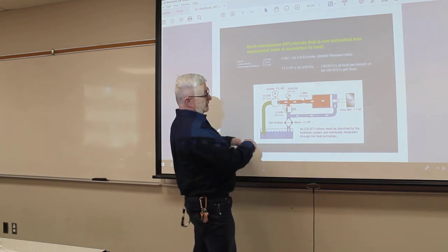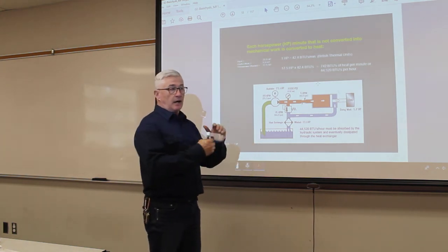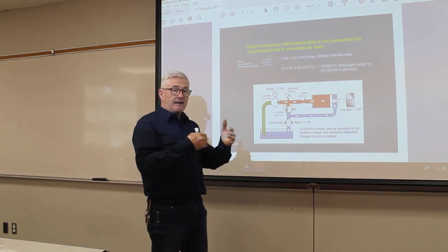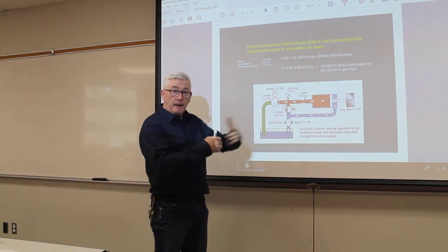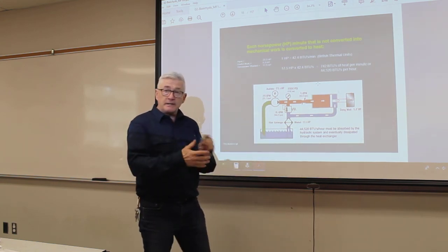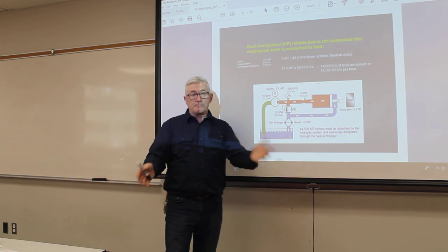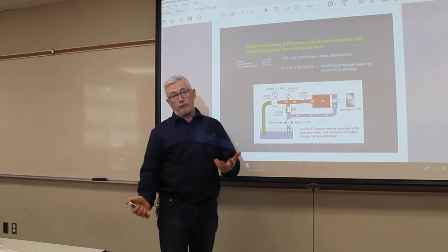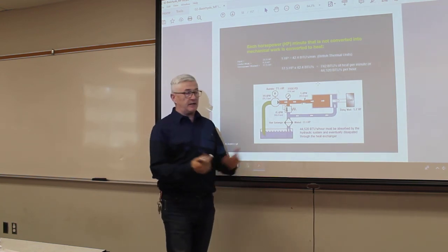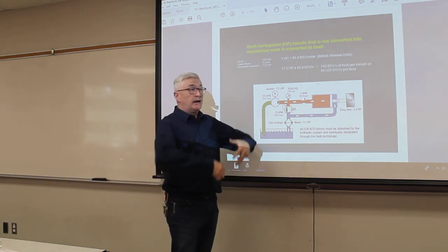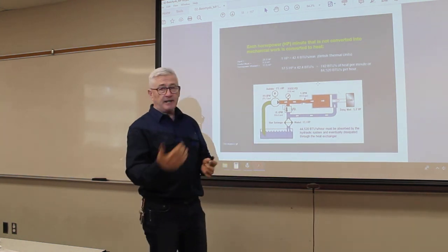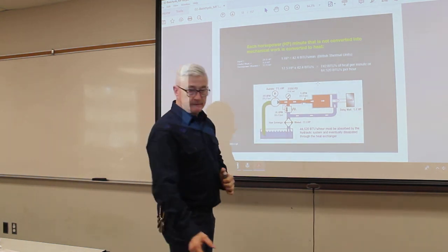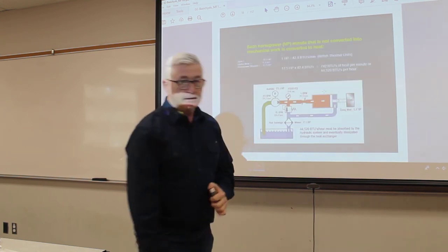That's why I'm going back to the other video where I said we look at how much horsepower it's going to take to drive the pump, and then try to have an input motor, a prime mover, that matches that design. We wouldn't take a 350 small block Chevy and put it on a wood splitter to operate it, because it would be wasteful. We would burn way more fuel than we would need to do that. You see a little Briggs & Stratton or something on there, and it does the job fine. So you match your input, your prime mover, to what you need to get the work done. All right, that's that one.